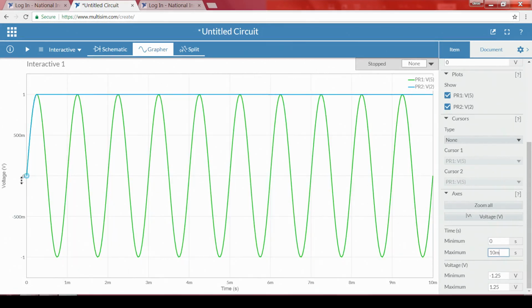If we observe, the output initially keeps on increasing, meaning the capacitor starts charging, and it is charged to a value of 1. Why only to 1? Because the peak voltage that we applied is only 1 volt, and since we do not have any discharging path, the capacitor is always at this particular point.